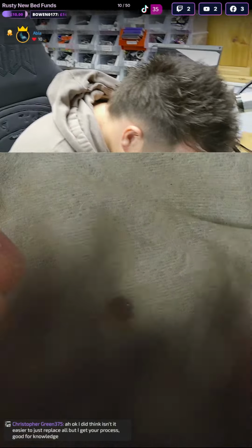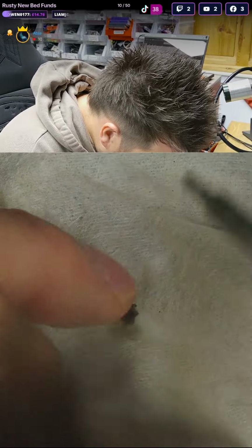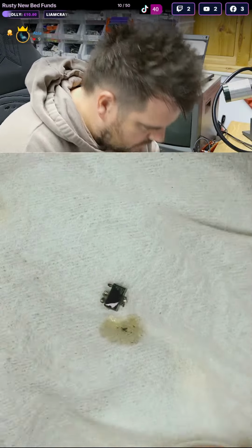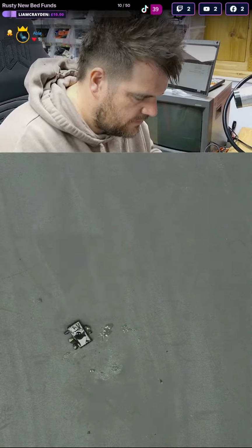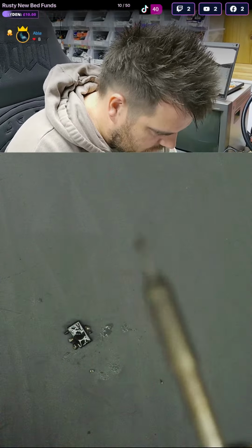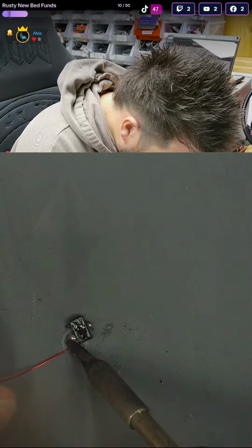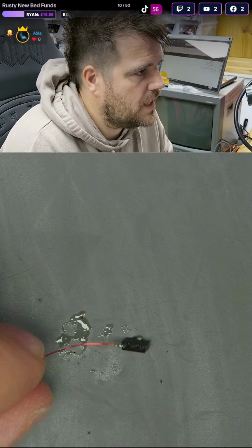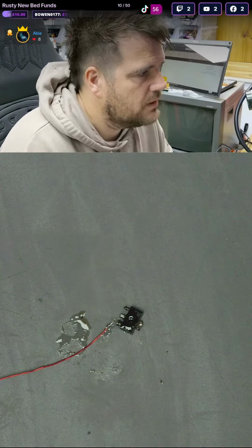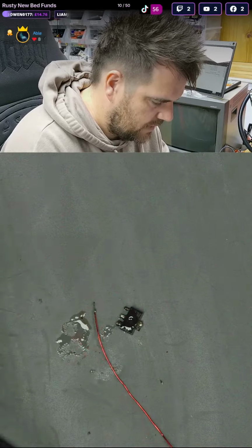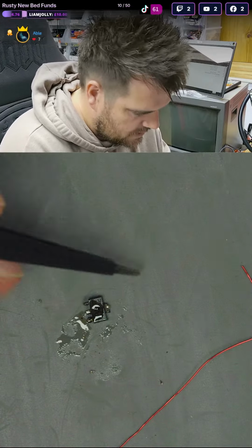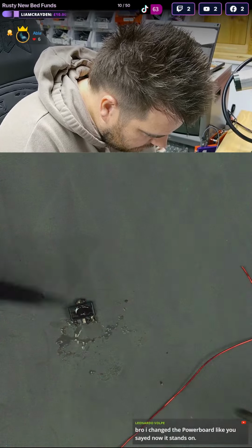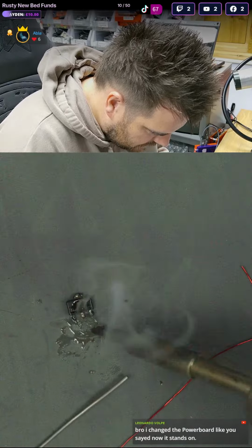So that's not going to work. Just going to have to let the flux go onto my desk. I was trying to prevent the flux going on my desk. There we go. And this is just difficult to tack on because it's still barely tacked on. Yeah, look, it's just because it's got dirt. I'm going to have to clean the pins then. I was trying to not risk damaging it by not cleaning the pins, but we're just going to have to really clean them pins up. Otherwise, we're not going to get wire attaching to them.